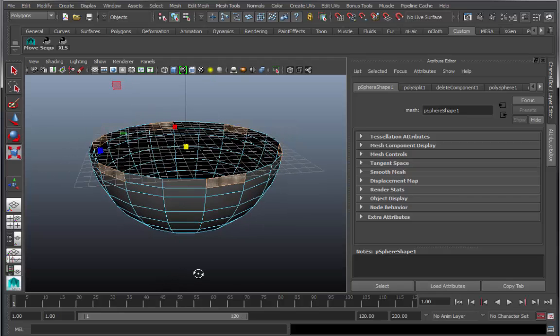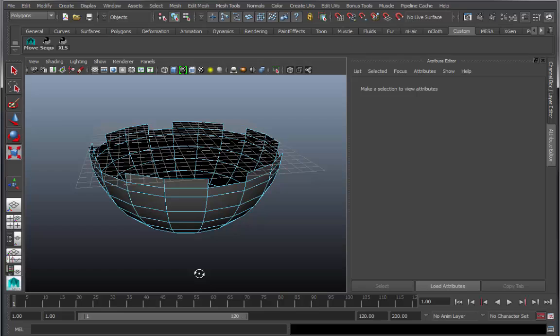So with this specific pattern, and you should have this saved already in case you make a mistake, with this specific pattern of faces selected, simply press the Delete key on your keyboard under the Insert key, and you should see those polygons disappear. Now we're ready to select the upper edge of this and extrude it in so that we have kind of a thickness to this. As you see, it's all very thin. We want to give this a thickness.